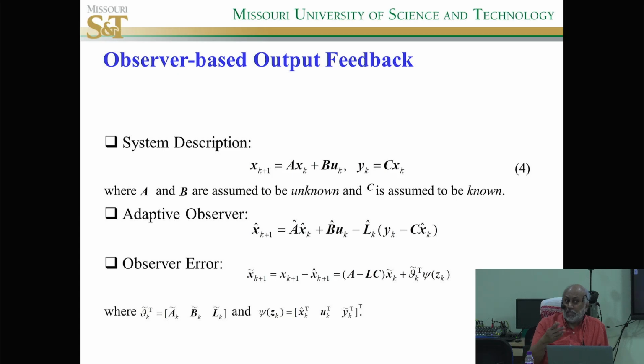So if it's a 6-cylinder, you divide the 720 degrees by 6. Or if it is 4 cylinders, you take 720 divided by 4. So 360 is one rotation, right? I hope you guys are clear about that. So we use 2 rotations, 720 degrees. Okay? So remember, you got to have that.